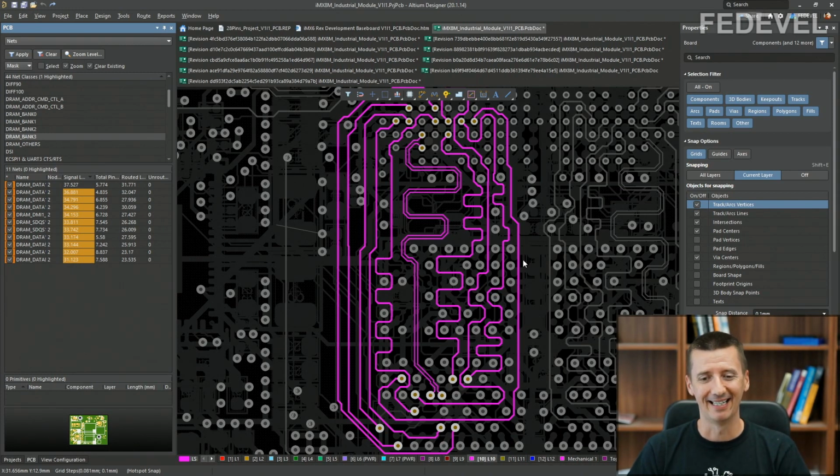I've been there, and I learned that doing the precise length matching is one of the latest things you may want to do in your PCB layout. It is one of the last things you do in your board, in your PCB layout. Precise length matching. Don't do it now. It will be wasted time. So just doing this approximate length matching in this draft layout is perfectly fine.